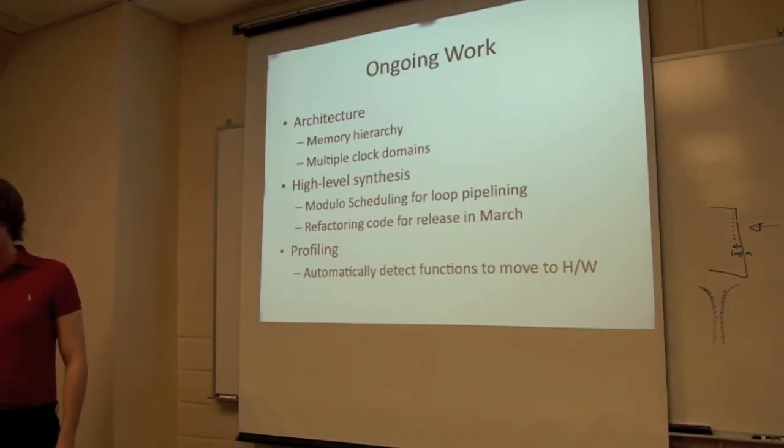I have a feeling it's quite far off because the hardware we generate is fairly naive in that we just have the state machine and everything's fairly sequential. We mainly take advantage of instruction level parallelism. Like I mentioned, there's no loop pipelining. When you're actually developing hardware, you're pipelining things a lot more, you're duplicating a lot more. I think if you did it by hand, it would be a lot faster. But that's just the whole research, extracting some of this parallelism automatically is part of the research here.